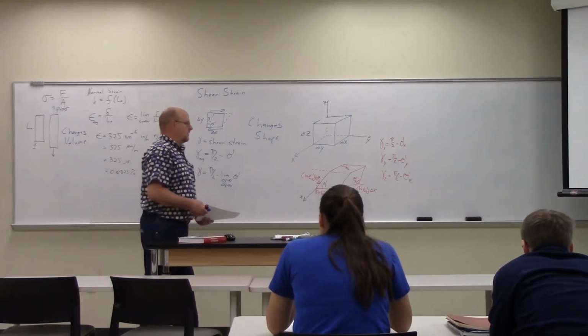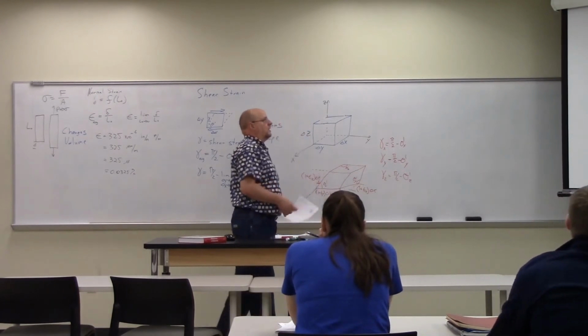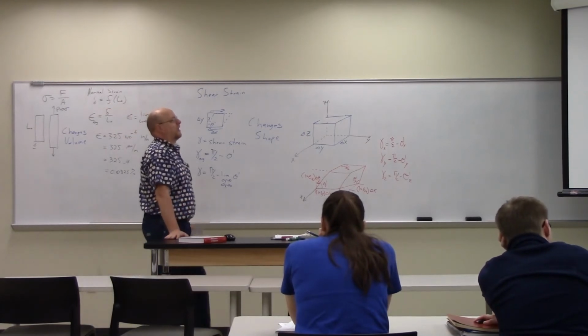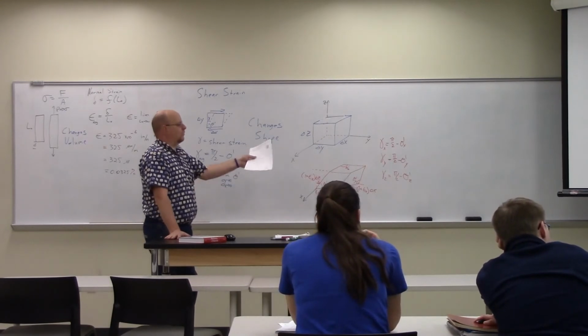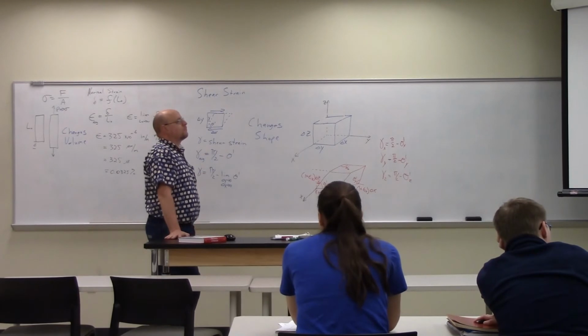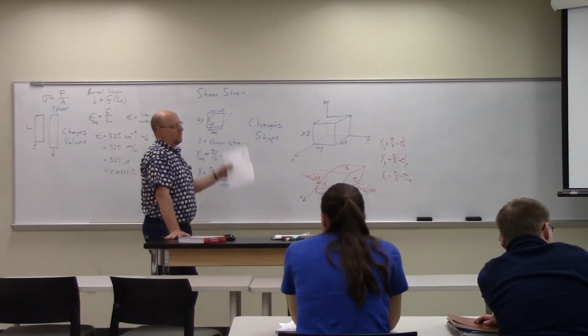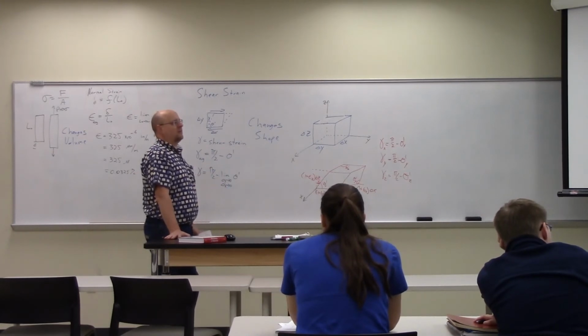Okay. All right, so let's do the two problems that we've got up here. Start with 213. The piece of rubber, so it's a square piece of rubber, is originally rectangular and subjected to the deformation shown by the dashed lines. So this is a two-dimensional representation of the same thing. Determine the average normal strain along the diagonal DB and the side AB.